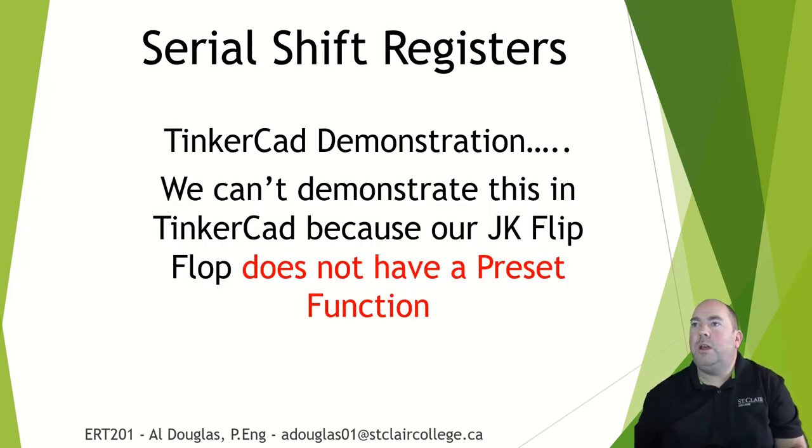Now, unfortunately, we are not able to create this one in TinkerCad because the JK flip-flop in our TinkerCad is not the same as the one that you have on your breadboard. Our JK flip-flop in TinkerCad doesn't have the preset function.